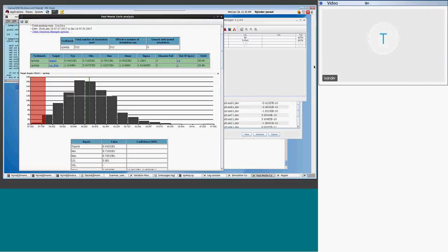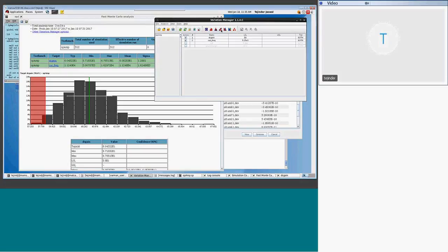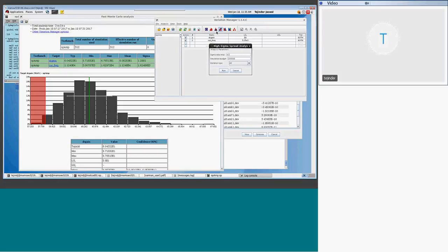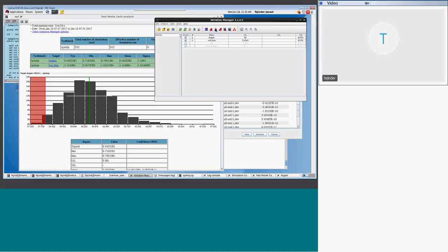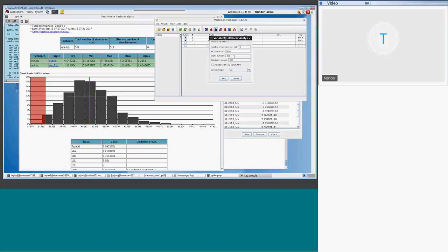If you have a high sigma analysis, or you can run another simulation, then you can define here, like I can do 3 sigma or 4 sigma. As I mentioned, it's going to increase your samples. See how the sample number increases here.